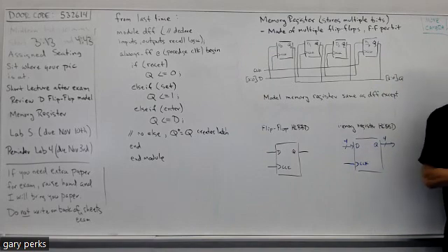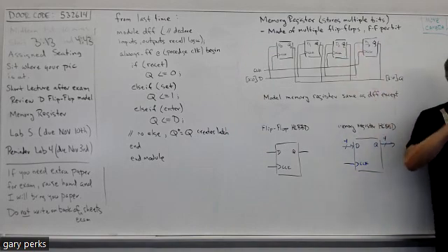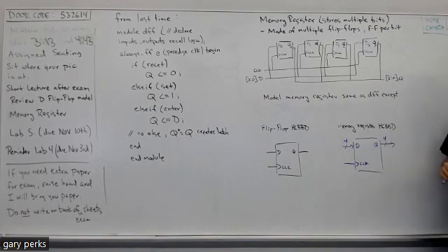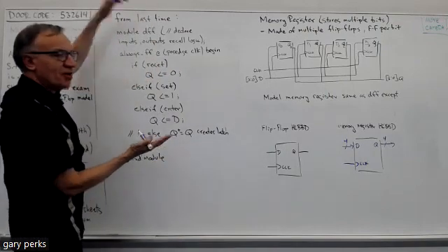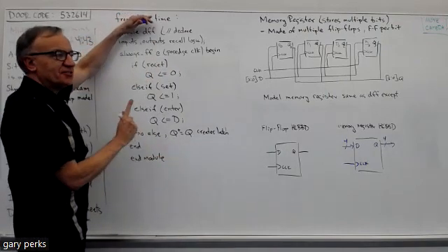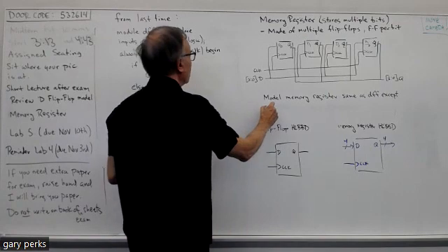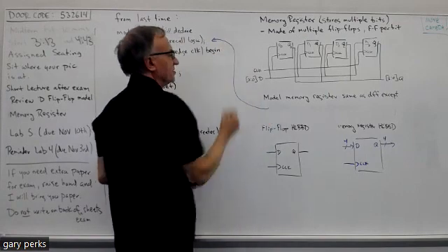But instead, we're going to have you let the software do that. Instead of doing that top module like you did with the RCA to connect all the individual lower modules together, what you can do is take the same code that you modeled the single D flip-flop with and just make some edits.